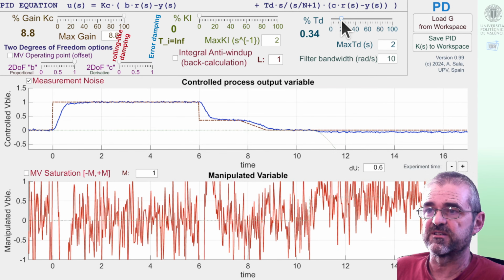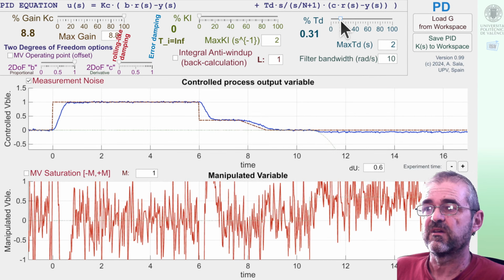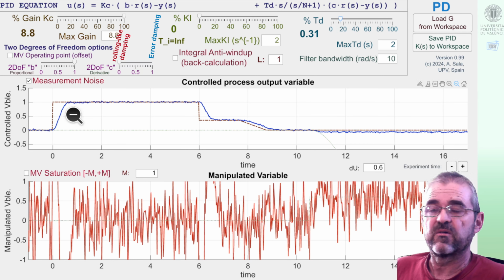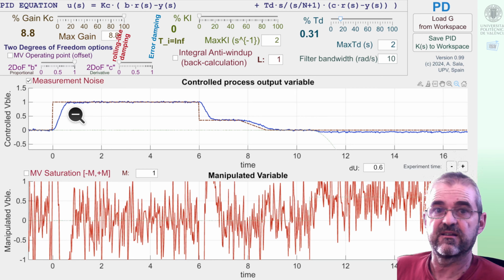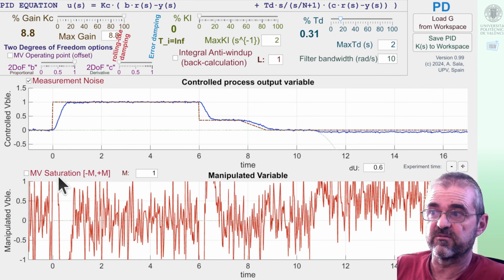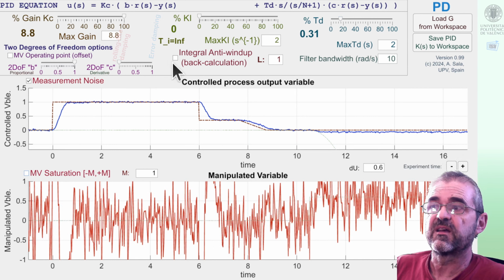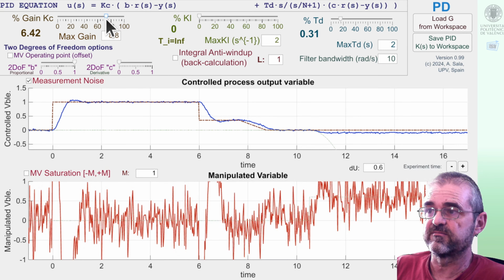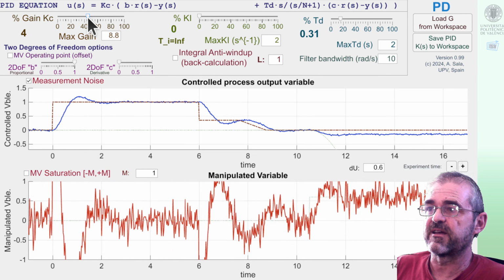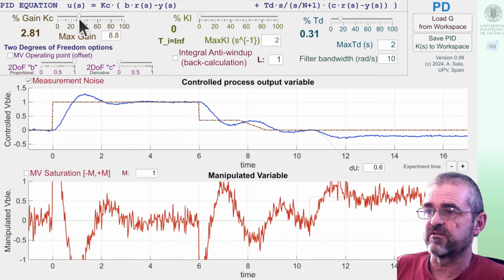Here we have a very nice damping, but look, we are achieving a settling time of half a second, and that is too fast according to my saturation limits. I just asserted previously that faster than 1 second was not possible, and indeed if I turn saturation on, things take 1 second, so I will reduce the proportional gain until my rise time is roughly a second.